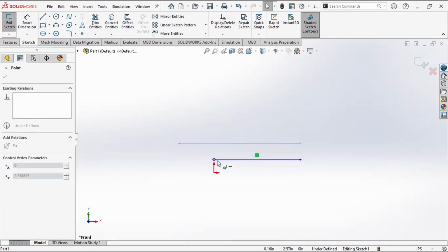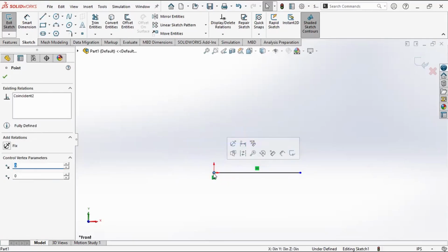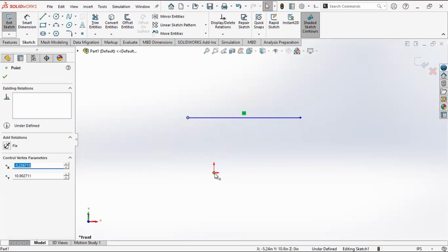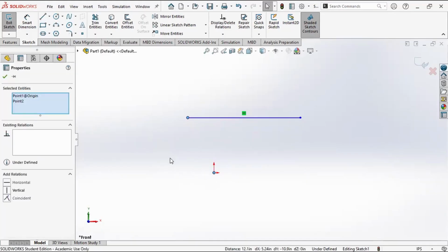I can also create a coincident by dragging it, and notice the little coincident icon that pops up next to my cursor when I release. It adds that coincidence. That is typically okay for these first few shapes that we put in a sketch. As the model and our sketching get more and more complex, I really want to do it the other way, the first way that I showed with control clicking the 2 points. It's safer. There's less things in the way.